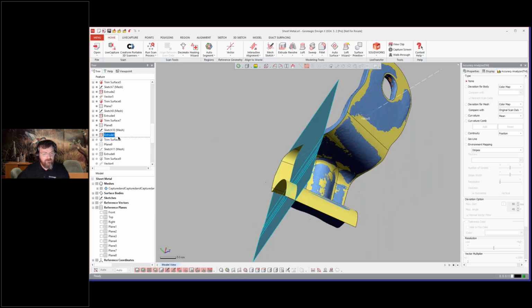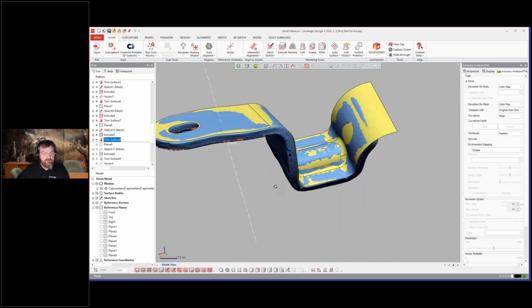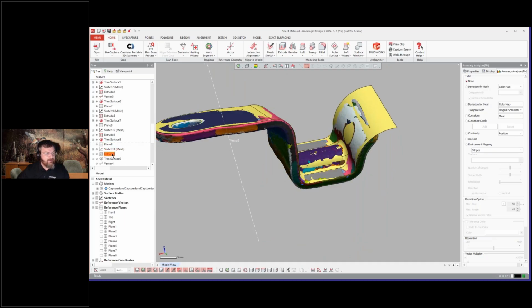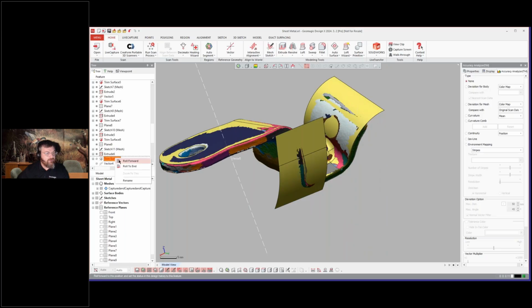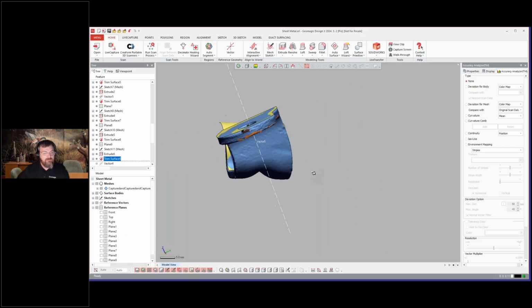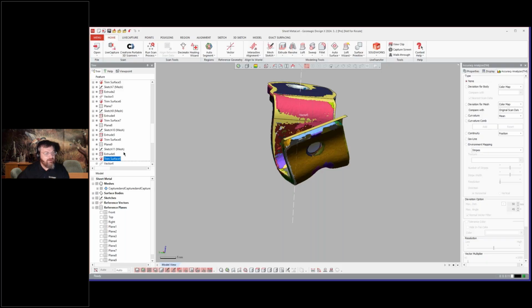And there are advantages to doing this, because you can just trim the top and create that zero thickness surface and then thicken it here at the end. So you can see here, trimming all these different areas off to make them exactly what we see it to be in the scan data.